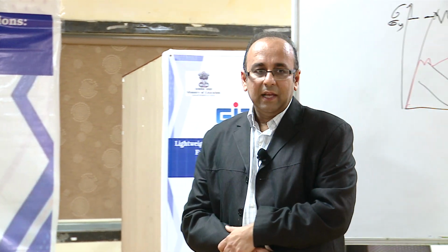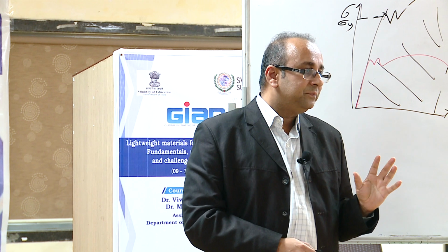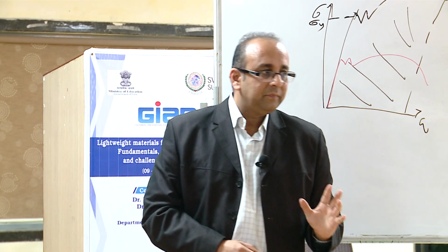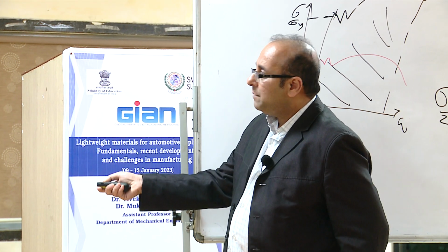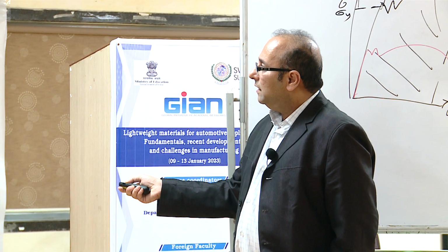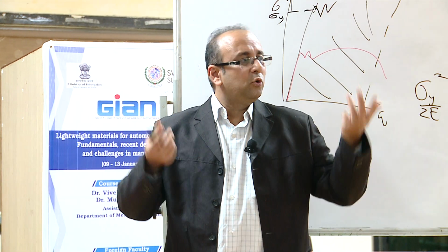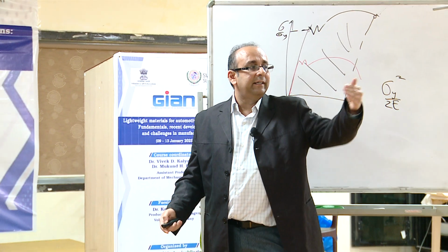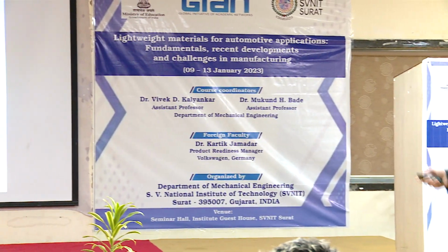Now, as I told you, our lecture is optimization of material to highest extent. We don't want to give a single gram of material where it is not needed. And this is done basically on the side panel. You can see this side panel. Normally, if it were 30 years back, I would have the same material, 1.2 millimeter, or maybe 1.5 millimeter, based on the highest material thickness which I needed. So for example, if I need 1.9 here, I have complete 1.9 millimeter material.